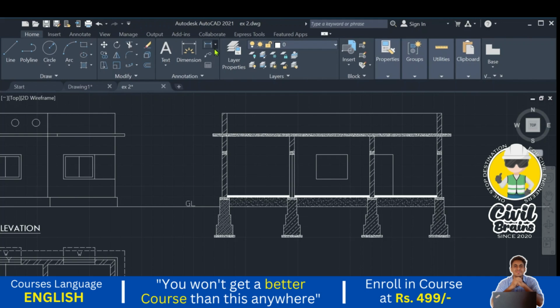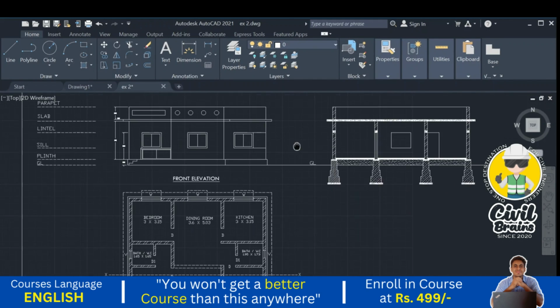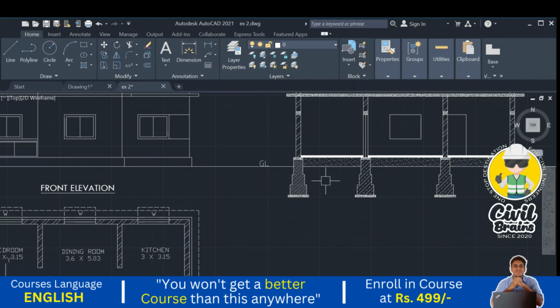Okay, I just show the dimensions here. I go to the dim style, modify, primary unit 0.0 I just take, text I just reduce 0.1 I just take, and arrow size also I just take 0.05 because the size is little. So here also you can easily do this one. Okay, so first